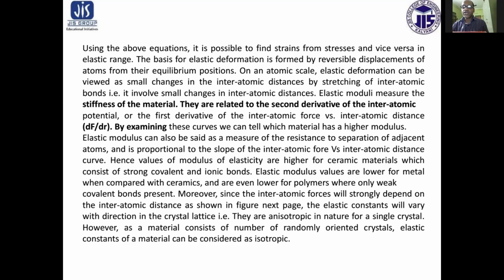Elastic modulus measures the stiffness of the material. It is related to the second derivative of the interatomic potential, or the first derivative of the interatomic force versus interatomic distance. By examining these curves, we can tell which material has a higher modulus.